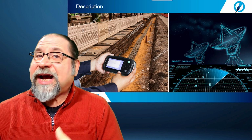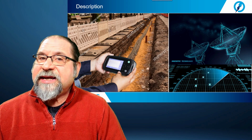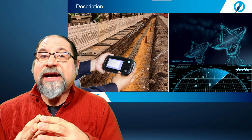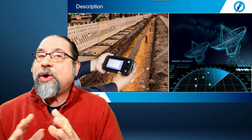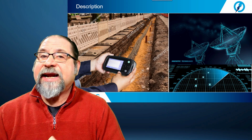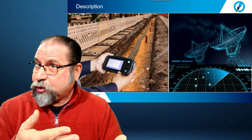Now, a Time Domain Reflectometer, or TDR, measures reflections along a cable. In order to measure those reflections, the TDR will transmit an incident signal into the cable and watch for reflections. If the cable is of uniform impedance and it is properly terminated, then there will be no reflections and the remaining incident signal will be absorbed at the far end by the termination. Instead, if there are impedance variations, then some of the incident signal will be reflected back to the source.